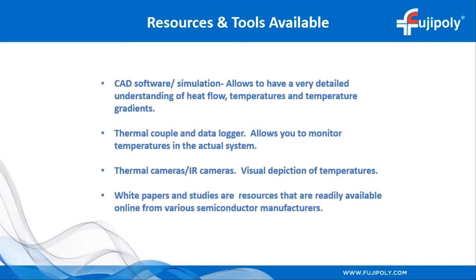And then there's also more of a physical real world tool, which would be thermocouples and data loggers. If you have some kind of prototypes, or some device that you could test on, you could attach the thermocouples in multiple locations wherever you feel you need them, and you could actually log that data and see how it performs over time once it reaches a steady state condition. You could visualize where the spikes are and where you might need to put some additional design work into.